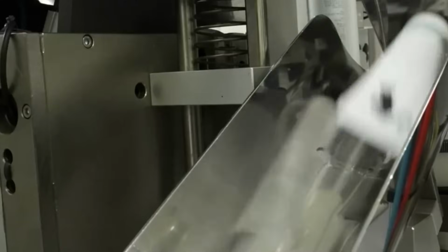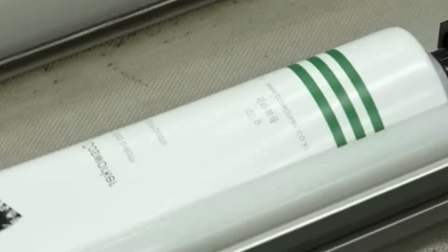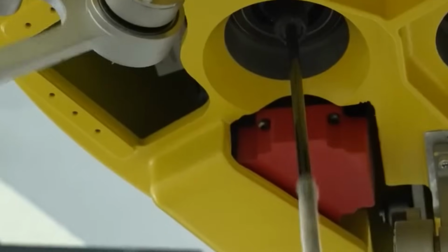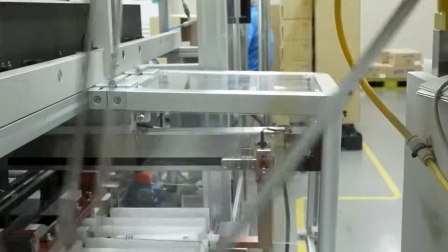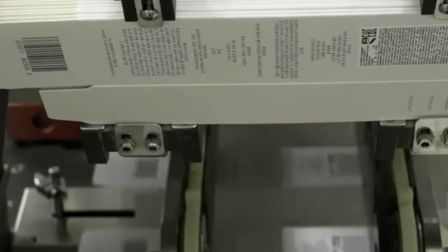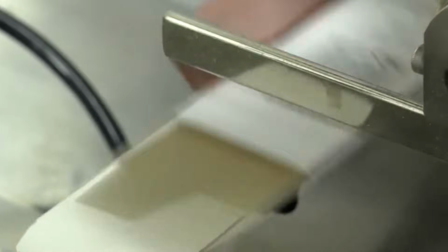Fluoride ion concentration is verified using ion-selective electrodes to confirm dosing accuracy. Toothpaste density is measured using vibrating tube densitometers and compared against target values to ensure proper tube filling weight. Deviations are corrected by adjusting water content or mixing parameters.